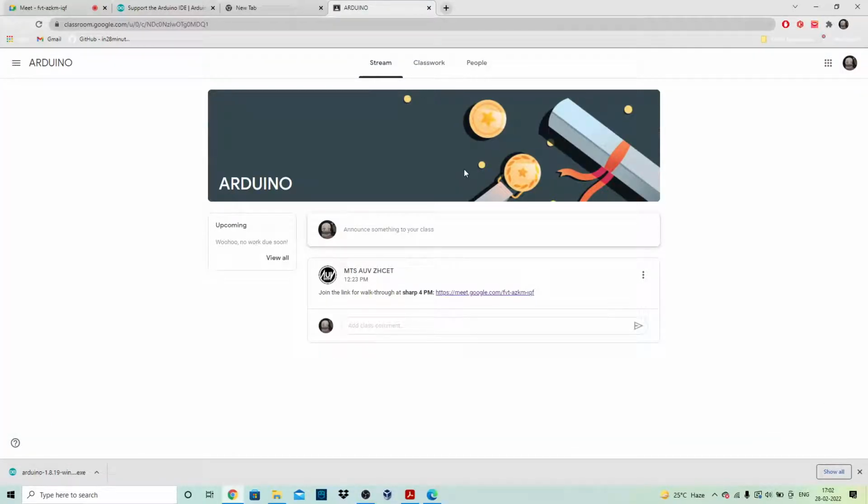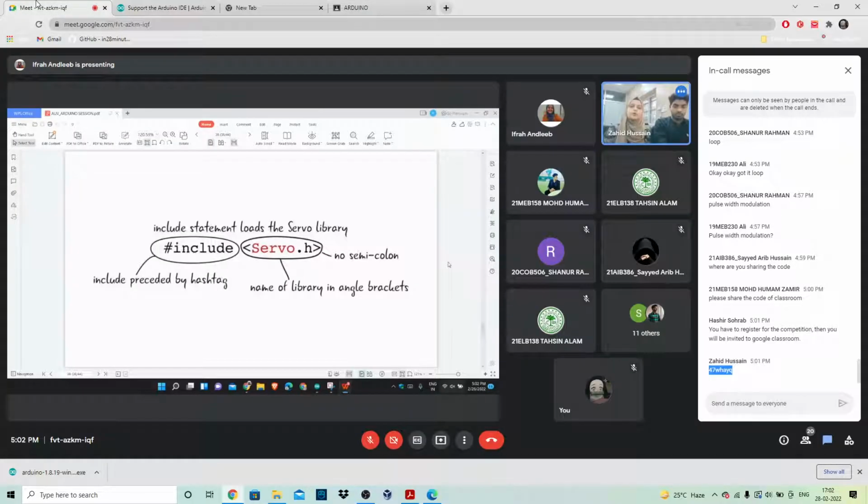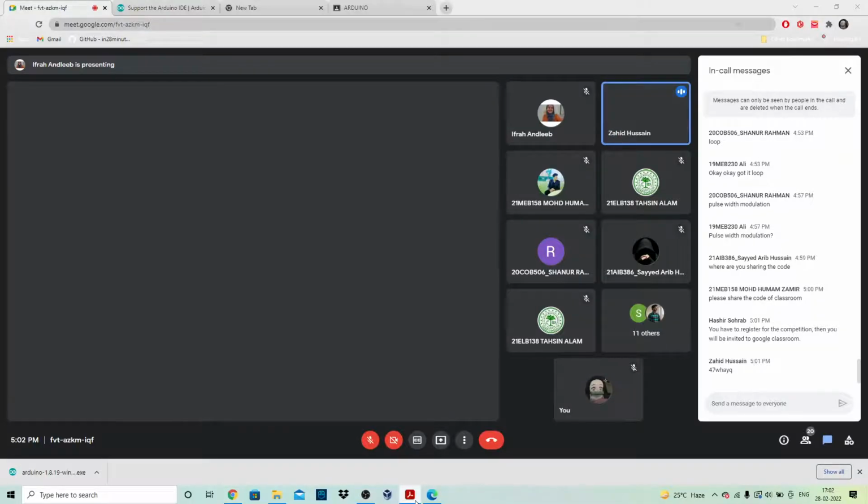तो हम उसको इनिशियलाइज अगर अपने कोड में कर देंगे तो हम बहुत सारे लाइंस ऑफ कोड से बच जाएंगे, राइट? सो दैट्स व्हाई बिफोर इनिशियलाइजिंग द सर्वो मोटर हम यहाँ पे एक लाइब्रेरी को इंक्लूड करते हैं, विच इज द सर्वो मोटर की लाइब्रेरी. तो इंक्लूड करने के लिए हम क्या लिखेंगे? सिंपली एट द स्टार्टिंग हम लिख देंगे #include और servo.h. इससे हमारी ये लाइब्रेरी ऑलरेडी आपके पास आ जाएगी. तो हमारे नंबर ऑफ लाइंस कम हो जाएंगी इन आवर कोड, राइट?